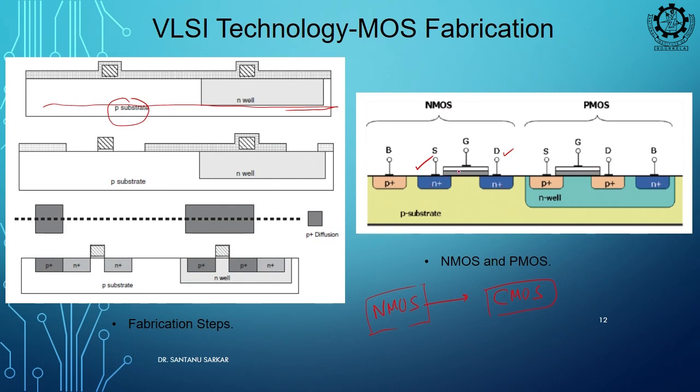So, on top of it then what you will do? You will grow an oxide. How you can do that? At a certain high temperature you can pass oxygen, right. Then an oxide layer will be grown throughout the wafer, then where you do not need it you can etch it off by using several kinds of chemical etching or physical etching, but this is grossly the technique, right.